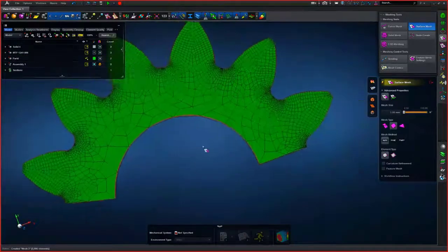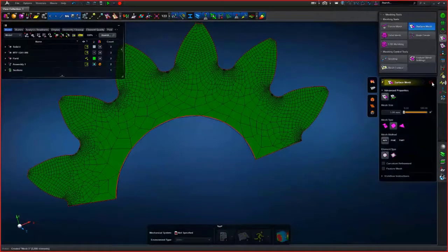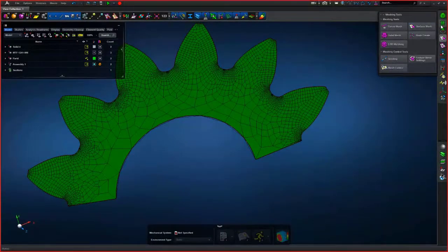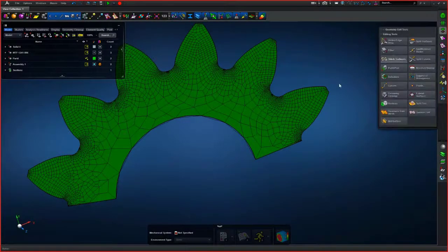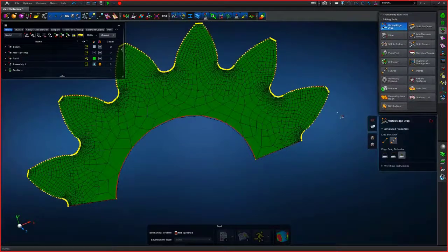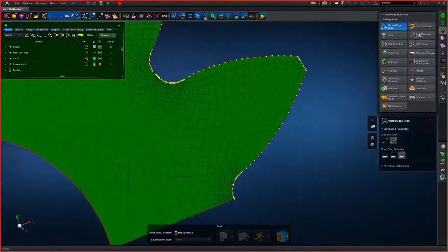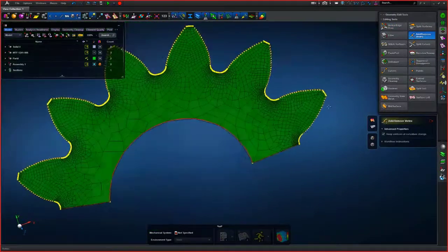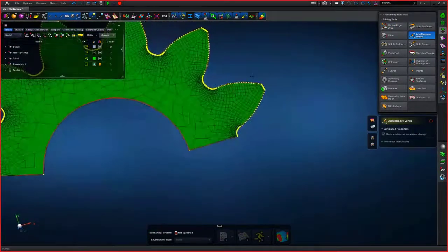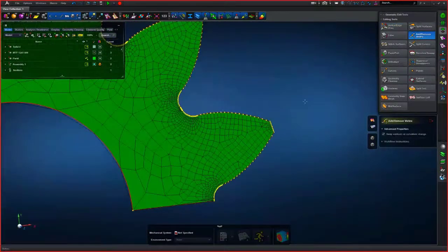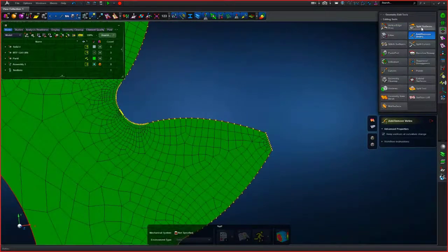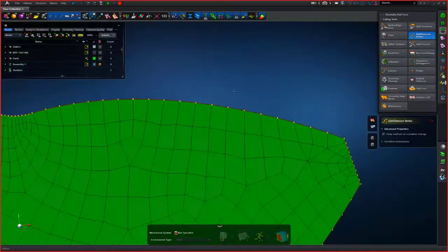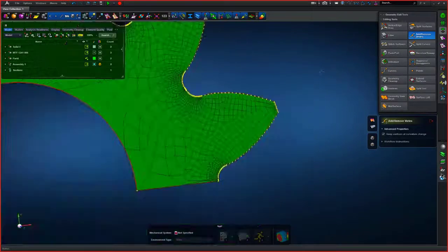And the reason this is happening is all those vertices that one can actually see when highlighting the vertices in this case. A quick way to get rid of these: you can never ignore these unless you suppress them.